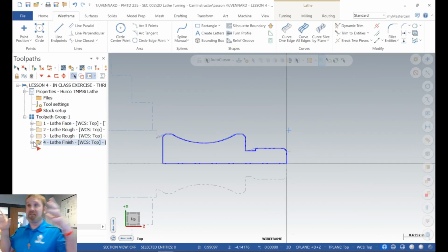If you have it on a mill, if you've got an umbrella tool changer, that thing's got to go all the way around to do a tool change. It's not like our side carousels where it just flips the tool down and they're already pre-staged and ready. Some lathes have very slow turret indexing. Some lathes are real quick, like our TM8s. Our TM6s take a second. The TM8s, it'll spin around pretty quick and scare you sometimes.